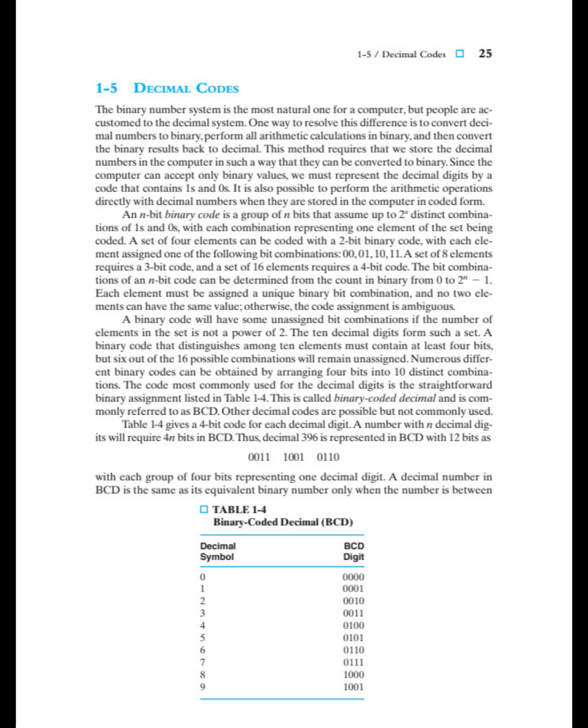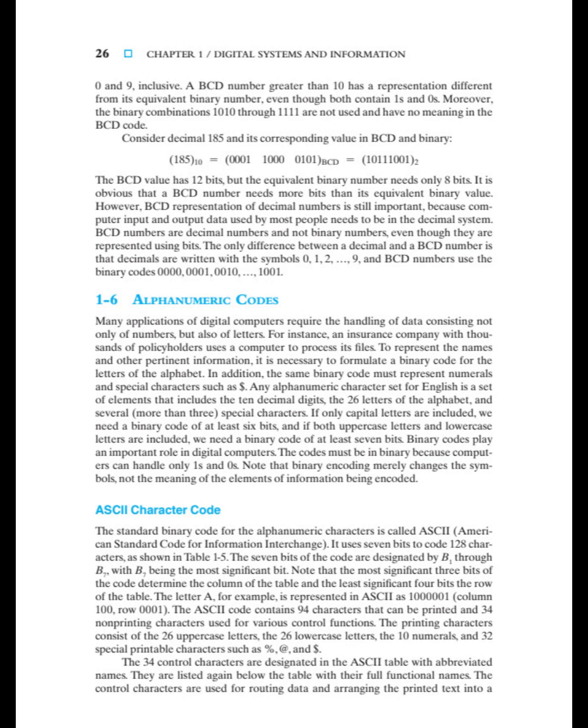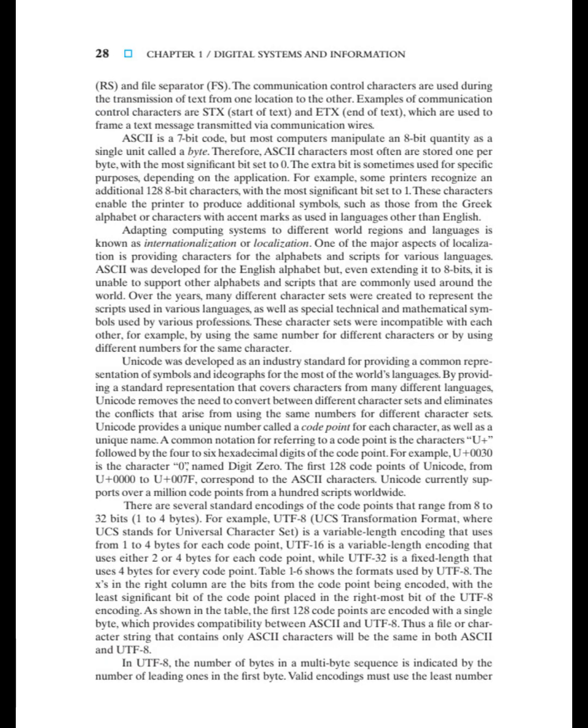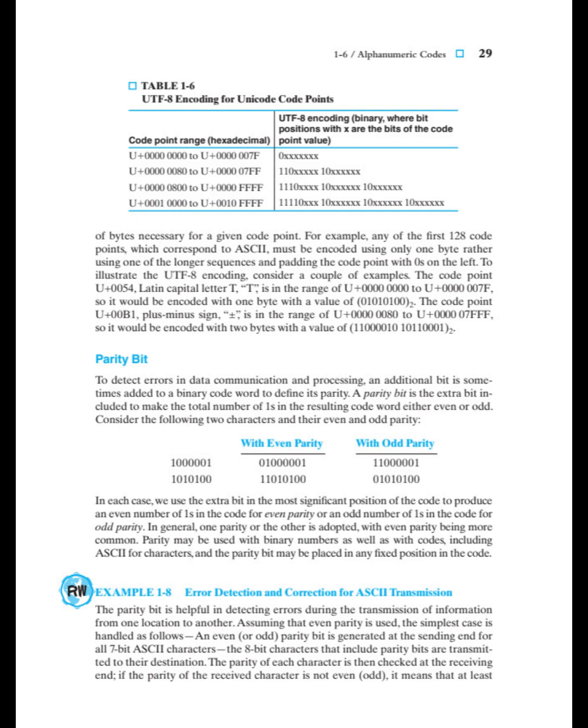But it's important to remember that BCD is not the same as the direct binary representation for values greater than 9. Right. 15 in BCD is 0001 0101, but in straight binary it's 1111. Exactly. BCD uses more bits, but it's easier to convert between decimal and binary, which can be useful for things like displays. Now what about text?